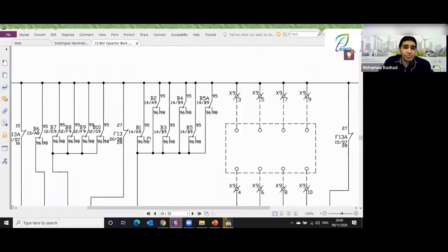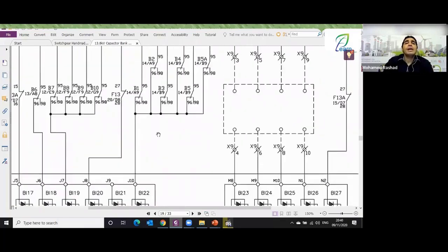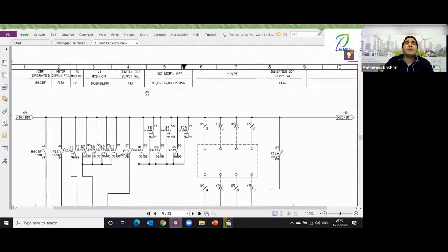If any of them trips, its contact returns to the normal close position, which is closed when the MCB is off. Therefore, if the MCBs are on, all these contacts are open. If one of them is off, the contact returns to the normal close position, connecting the DC here to this input, triggering an alarm immediately and sending it to the system.